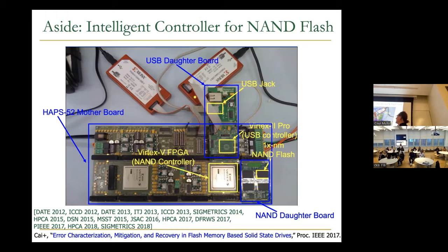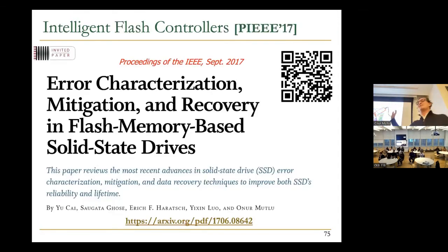What really makes this technology work is cooperation between the controller and the device. The controller really understands the voltage levels of the different cells. It basically tunes the voltage level such that you minimize the bit flips that you get. And controllers have a lot of error correction, etc. We have a lot of work in this area that I'm not going to talk about, but I think this is a fascinating area. I think a lot of the emerging memory technologies need this sort of controller going into the future as well. But this is one paper that we've written that summarized a lot of the research and industrial work that's going on in solid state drives.